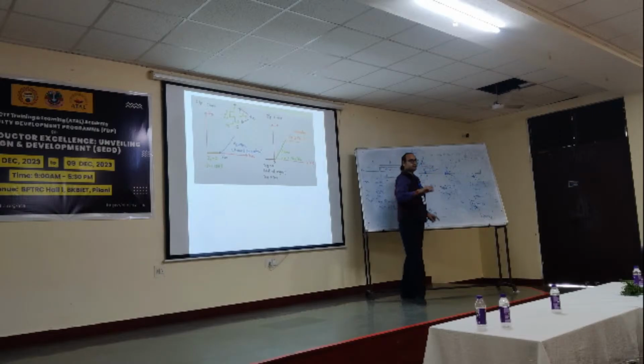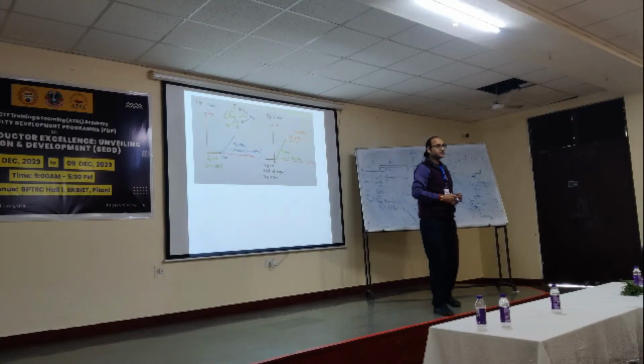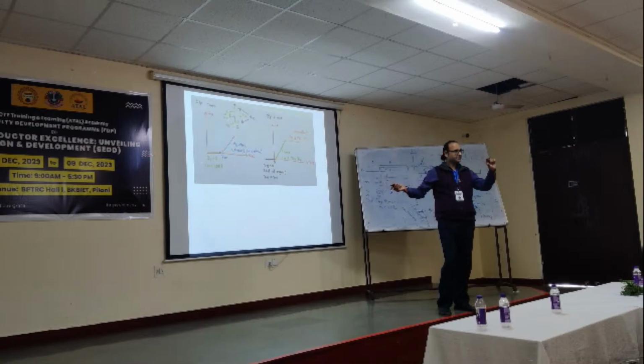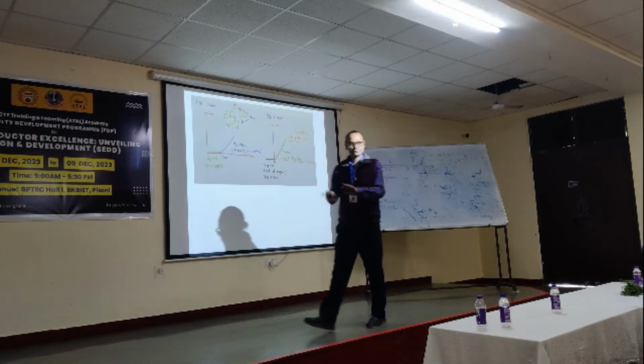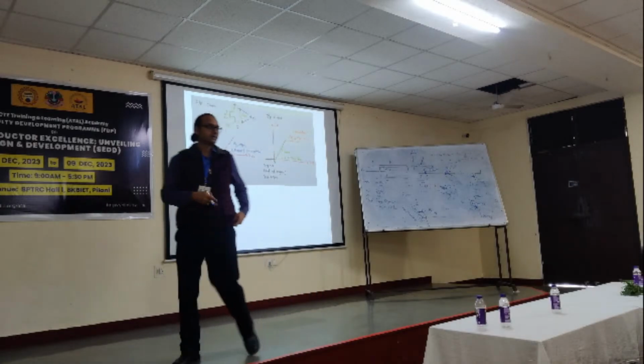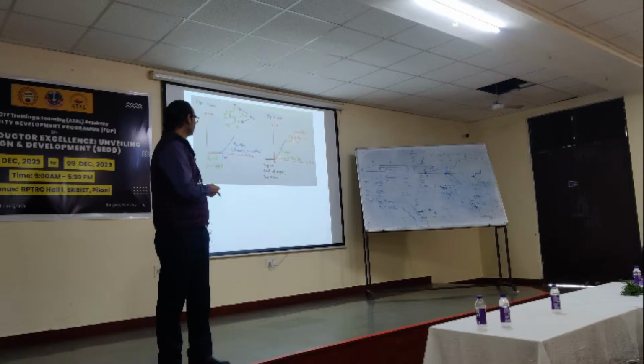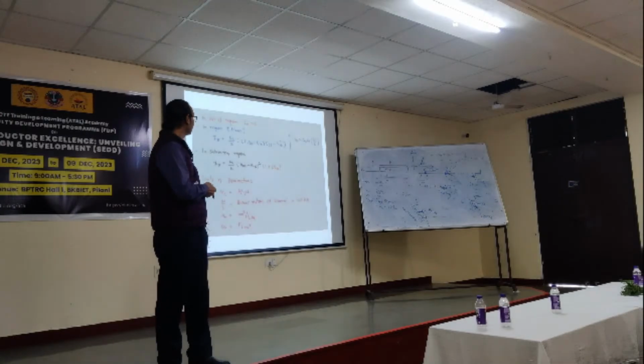The rest of the voltage drops across the external circuitry. Same thing happens here. Once threshold voltage is reached, there is a very small drop across the MOSFET itself, and all the other extra voltage is dropped across the external circuitry. Same thing happens here. And we know in the ID-VD characteristic, the linear region and saturation region.